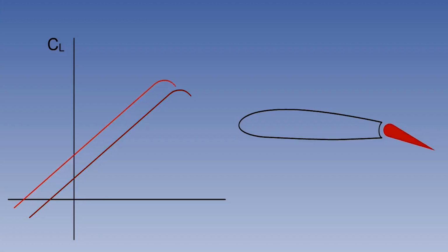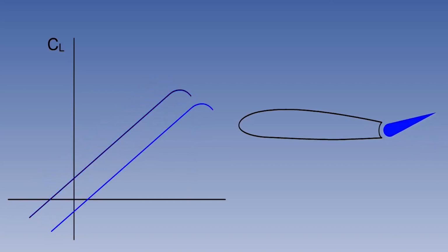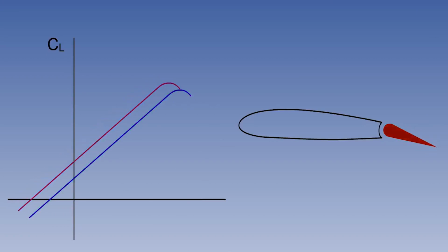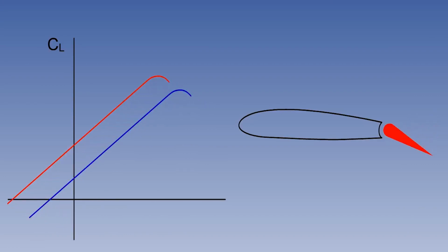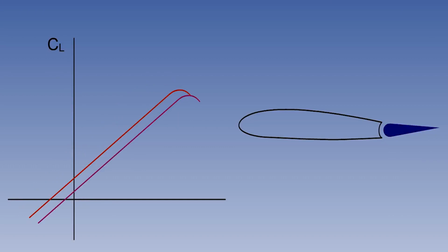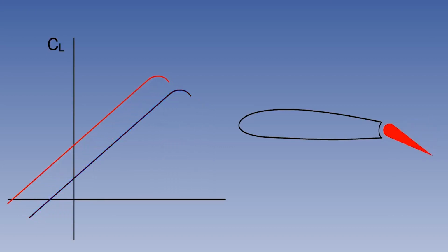The basic method of changing the attitude of an aircraft, that is, its position relative to the horizon, is by temporarily changing the camber of the airfoil of the wing, tailplane or fin, which will alter the lift it produces. The diagram shows the change in lift with changes in control surface position. The overall effect of a control movement will also depend on speed.